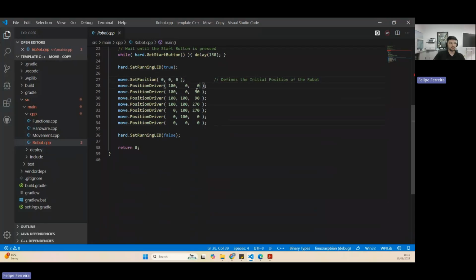Okay. Then my robot rotates to 90. Then my robot moves up in y. Then my robot rotates to 70. Then my robot moves in x, rotates again, and then moves in y. If you are talking about a robot that has 3 wheels, an Omni robot, I don't need to. I can combine linear with angular.